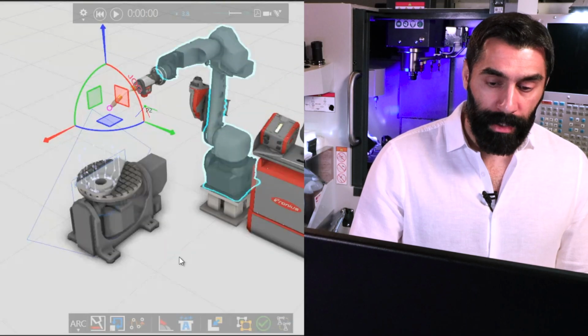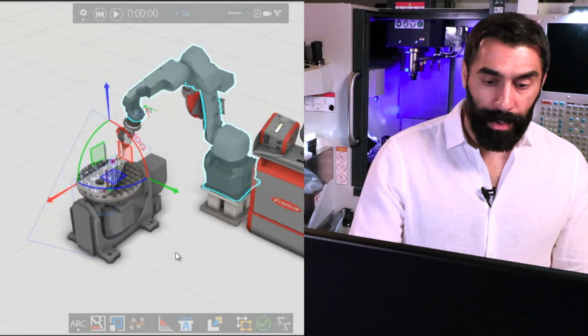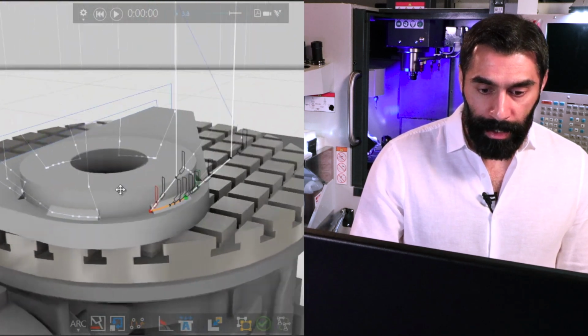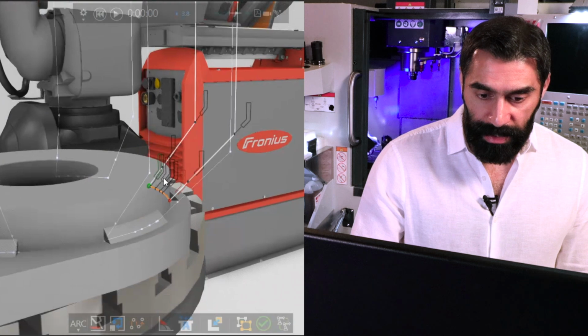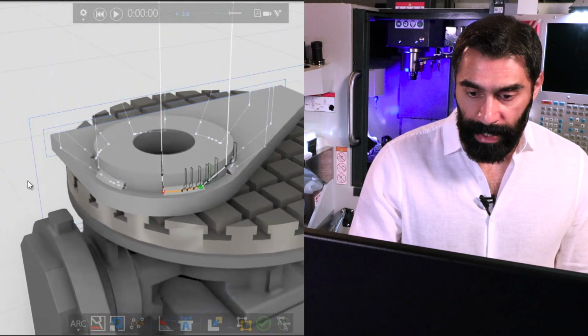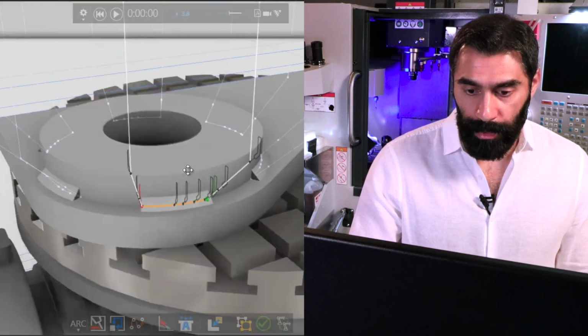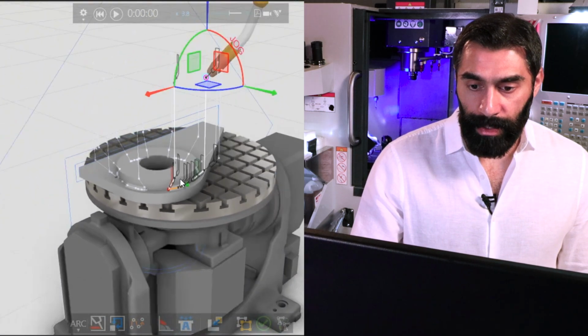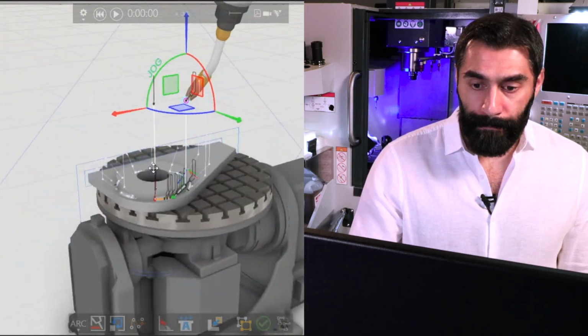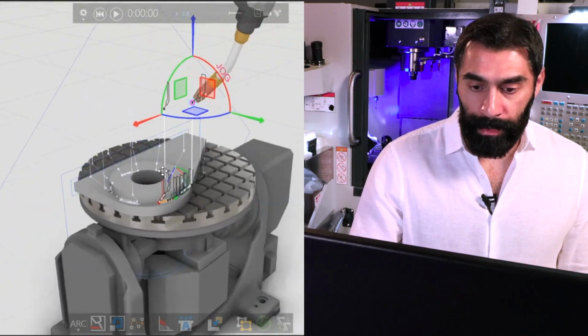On import, Visual Components automatically generates the weld program. So if we zoom in, we can actually see the robot positions that the particular simulated cell needs to go through in order to accomplish the welds. You can also see the points, the safe positions that the robot goes up to between the welds.